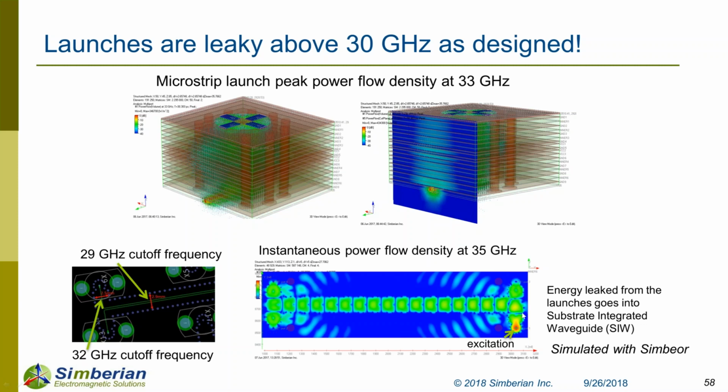This one shows power flow density between every single layer in there. You see it like this. It's multi-path propagation. Basically, the energy, in addition to going through the strip line, goes through the interplane area, through all interplane waveguiding structures. That's what happened.